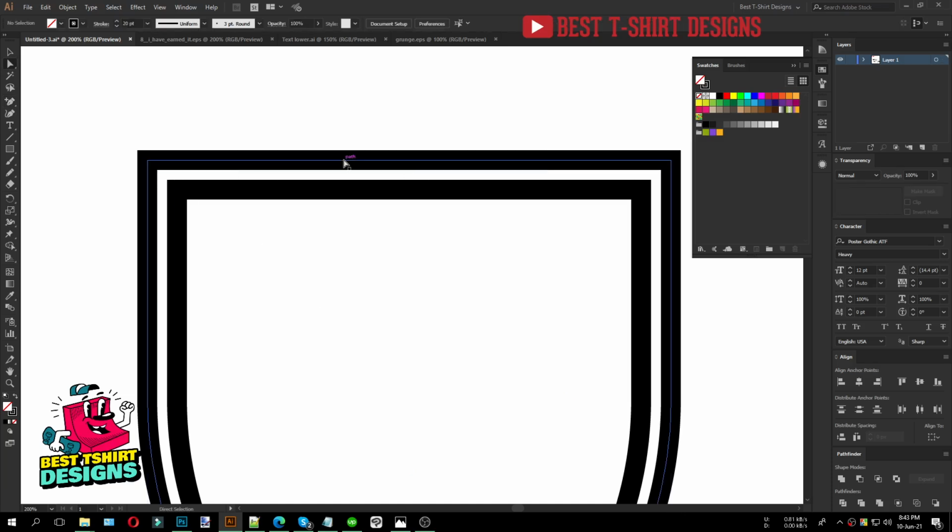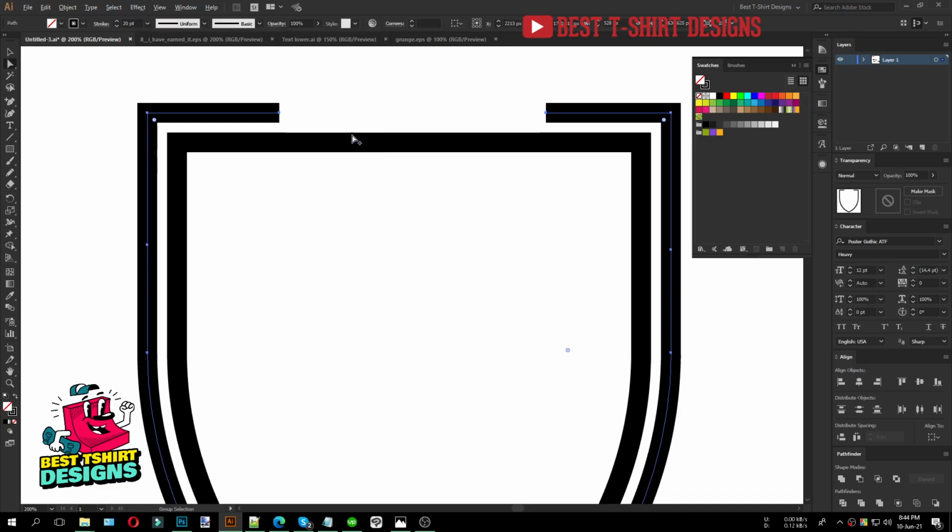If you want to select any part of a straight line, a stroke, then you have to make an in between anchor point. You have to make 3 anchor points, and then this is the 1, this is the 2, this is the 3. If you select the middle one and then delete, it will delete this part from this and this area. In between the area will be erased. So that's why you have to make 3 anchor points and select the middle one, press delete. That will erase it perfectly.